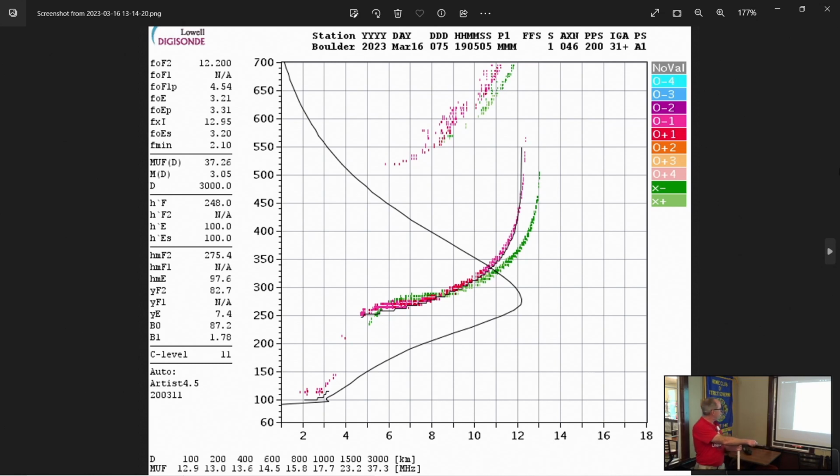You'll see here, MUF, maximum usable frequency. You'll see in some prediction or propagation reports, you'll see MUF. You'll see in software like VOACAP, you'll see MUF. That's maximum usable frequency. That's not what we're using for NVIS. MUF depends on going off at an angle and glancing down and going over the horizon. And you'll see here, they have higher and higher frequencies of maximum usable frequency, or MUF, based on how far out you're going, which means how shallow an angle you're going out.